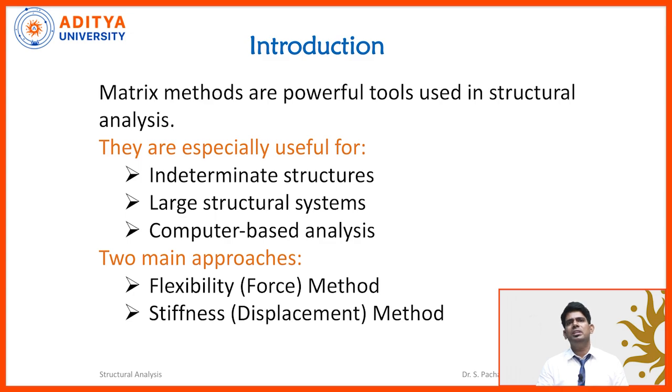They are essentially useful for indeterminate structures when the number of unknowns is more than the available equilibrium equations, and for large complex structural systems. Generally these two methods are preferred for computer based analysis, particularly the stiffness matrix method, which is more prevalently used for programming, and it is the solver in STAAD.Pro and ETABS.